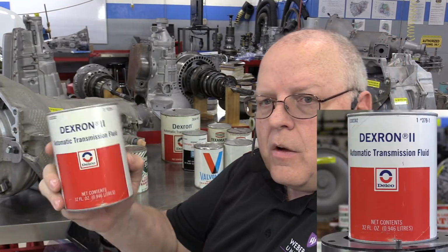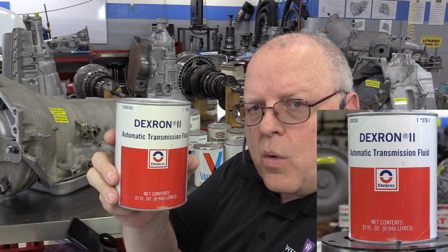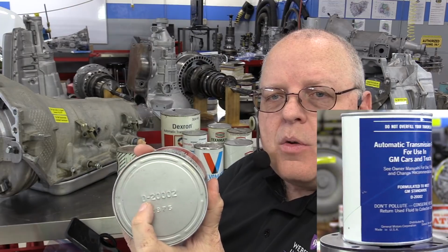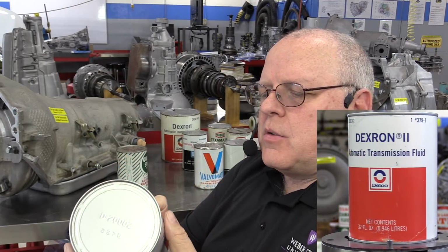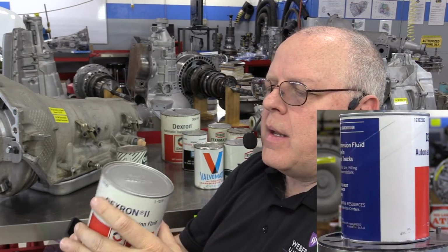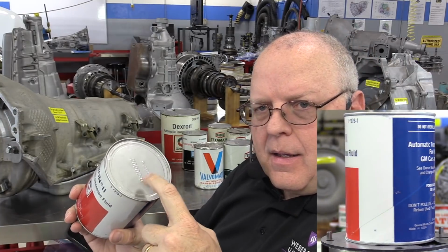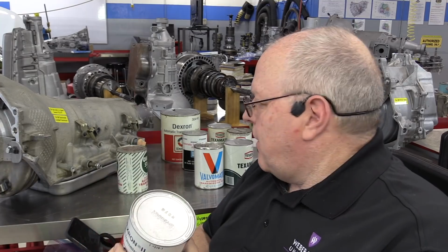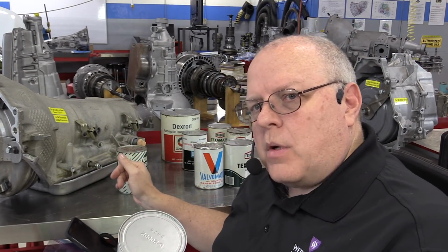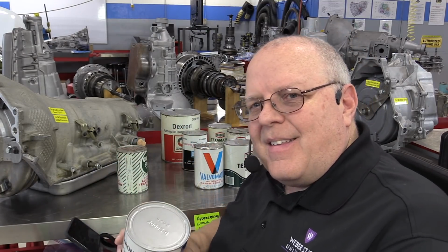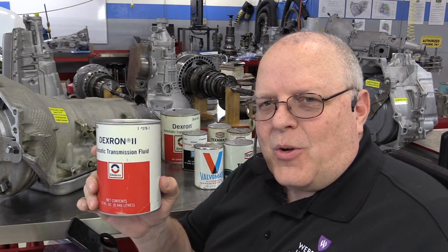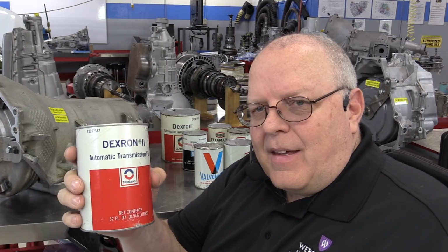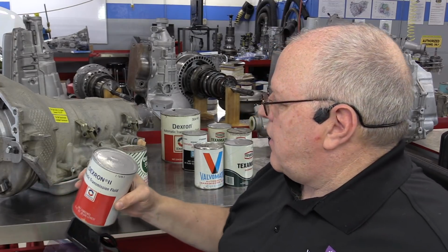So here's a can of Delco Dexron II fluid. It has a license number of D2002. So this is Dexron 2D. And the D doesn't mean Dexron, that's just, we had Type A, Type B was the original Dexron, Type C, that promoted cooler corrosion, and now Type D fluid is the next Dexron out there.